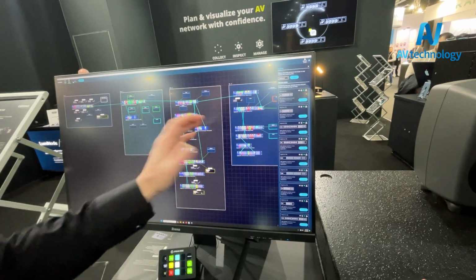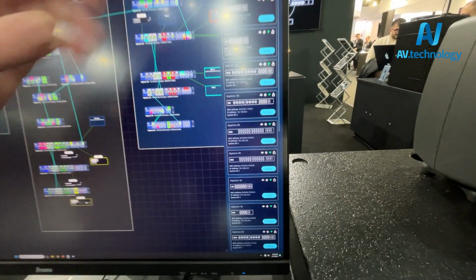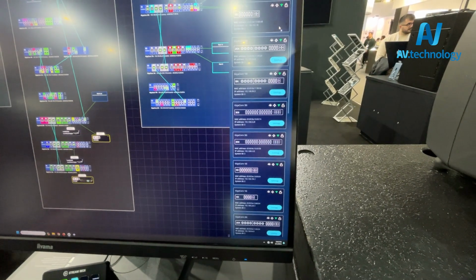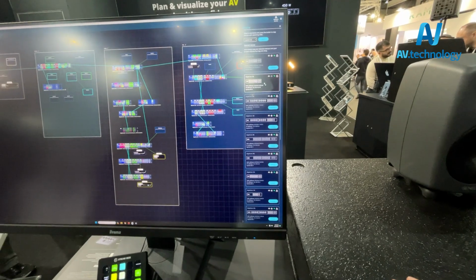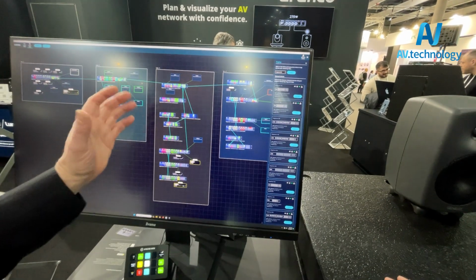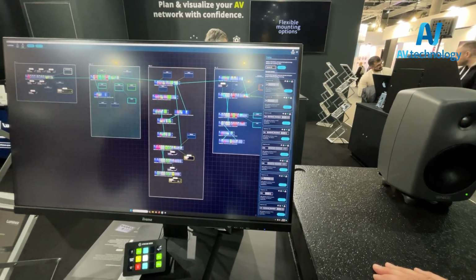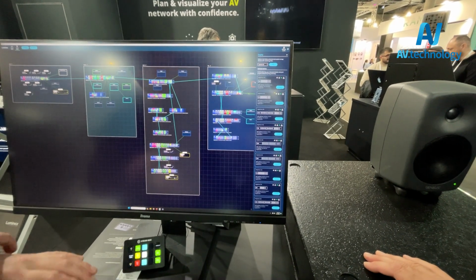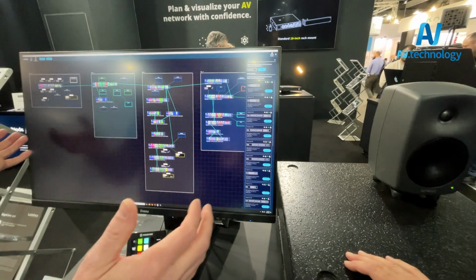So we can also deploy it, so you see a complete list of connected devices. And once you do this the first time, then they're unmapped, of course, and then you can just drag drop that switch on its position, and then you deploy the setting. It will check if all vital connections are there before you deploy, and 2 minutes later, from a blank unconfigured configuration, you have a full deployed network. So for installation integration, that minimizes commission time to a very minimum, and you have always full documentation of your setup. Also, if you change things in live, you just drag it back to project, and you can keep a full project of your full installation.